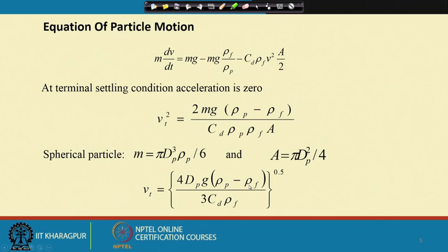Here there is a caution that the fluid density varies with the temperature. So, you must note down the temperature of that fluid and take that density. Normally, for simplification of our calculations we use the water density as 1000 kg per meter cube, but that is at 4 degrees centigrade. So, here rho f is the fluid density.